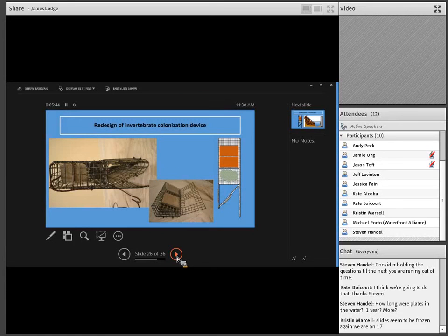The other thing that we did to keep those settlement plates on is that we have them in this prism arrangement so that we have different orientations. Then we make a cover based on that actual wire mesh as well, and we would secure that cover over the top of the settlement plates, basically to hold them on, rather than using cable ties or something like that.